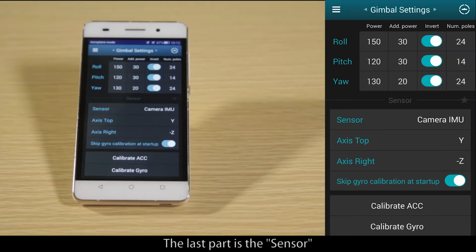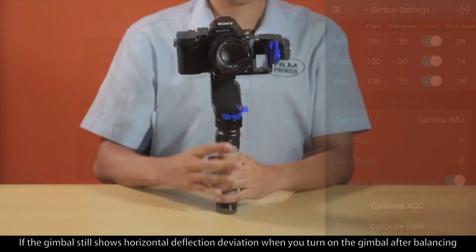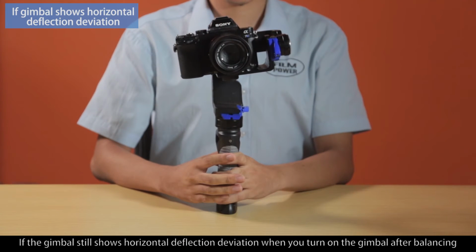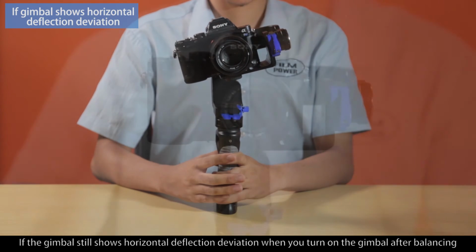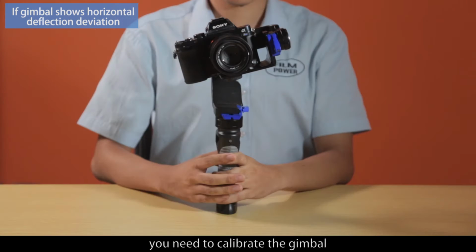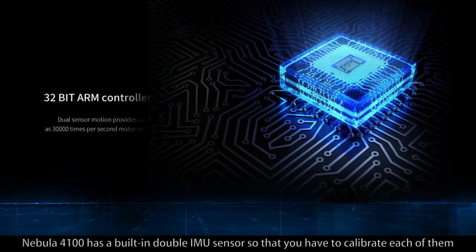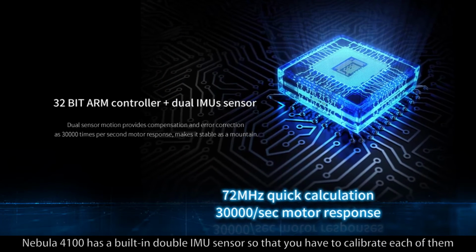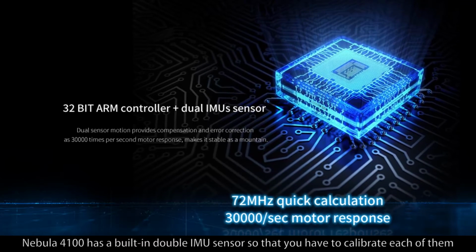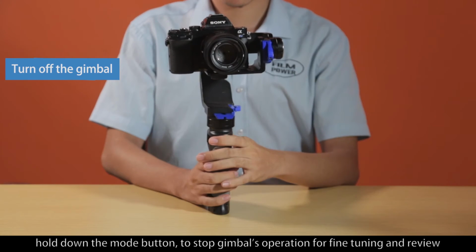The last part is the sensor. Previously, we introduced how to calibrate the gimbal. If the gimbal still shows horizontal deflection deviation when you turn on the gimbal after balancing, you need to calibrate the gimbal. Nebula 4100 has a built-in double IMU sensor, so you have to calibrate each of them. Hold down the mode button to stop gimbal's operation for fine-tuning and review.